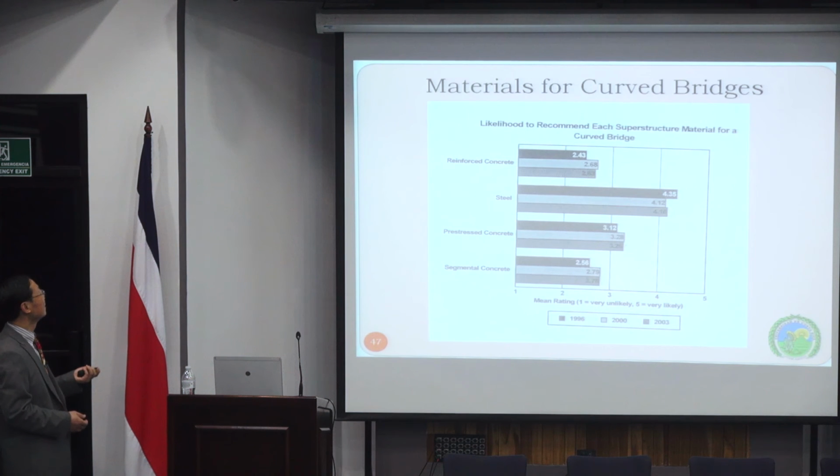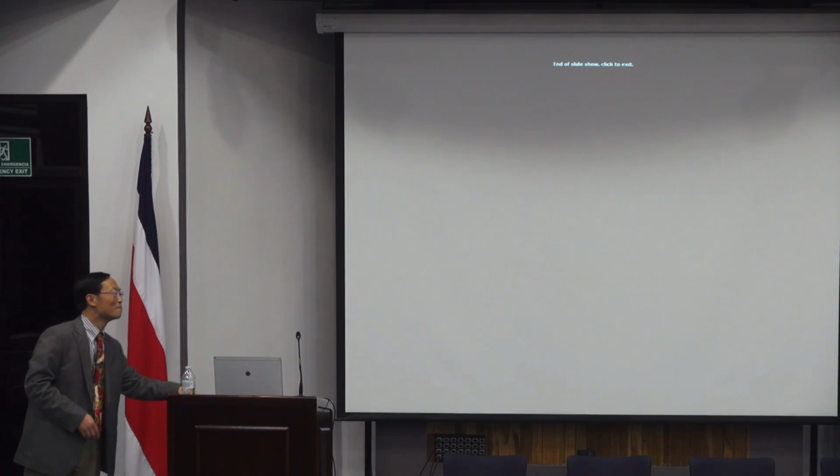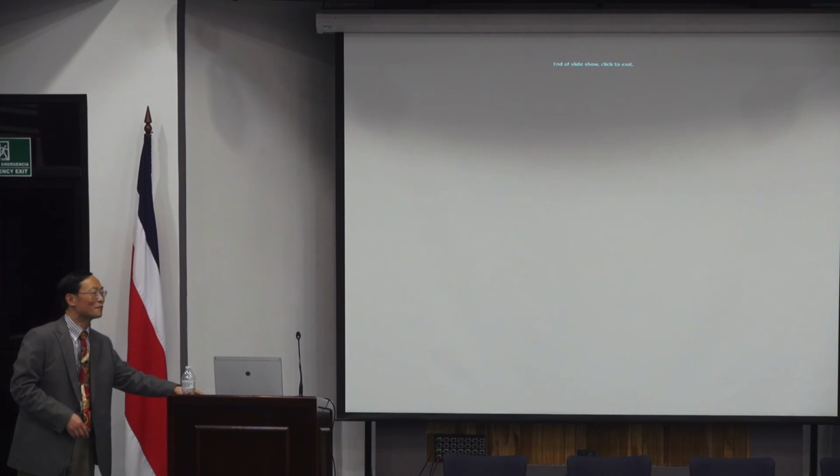And again, I think that is very similar for curved structures. Once you have a curved structure, steel becomes a lot easier because steel fabrication of any shape is much easier, and also a steel box has much better rigidity against torsion. So that gives a conclusion of decision making.